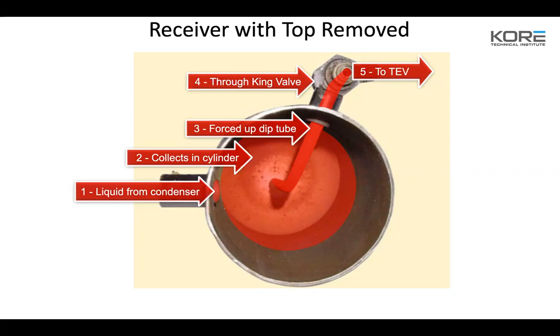Yep. So you haven't lost any refrigerant. You're just using that refrigerant to eliminate some of the capacity in that condenser. So the one thing you don't want to do is maintain the same level year round, because depending on what your valves are doing, you want to make sure that you're holding a good charge.